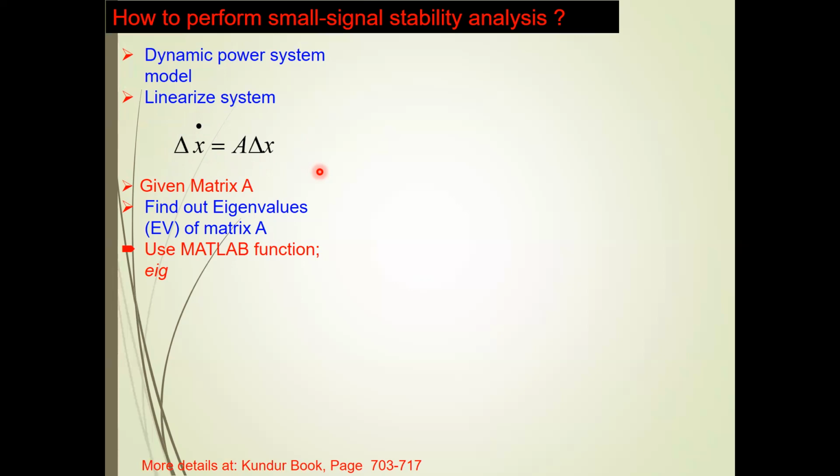So the state space. This is actually a form of the state space equation here. We have x1 dot, x2 dot, x3 dot. These are the state equations, and we derive them from differential equations, dx by dt basically. Here the term delta refers to the small change in the state variable, and it is the rate of change of that small change. This is equal to A times delta x, where A is the state space matrix.